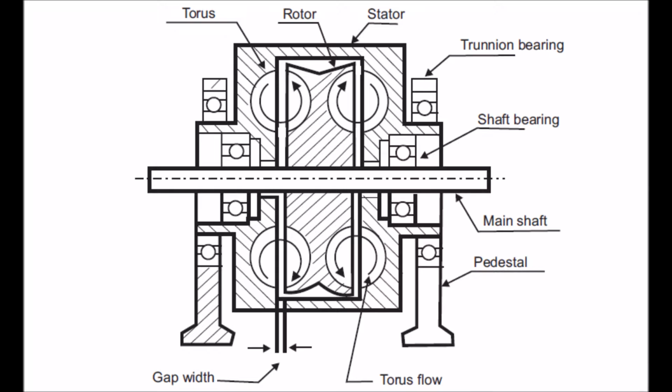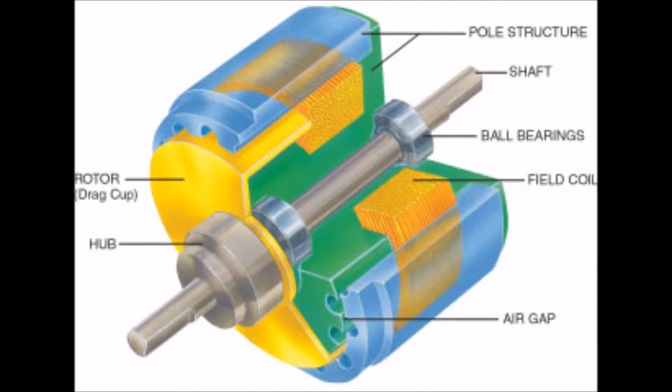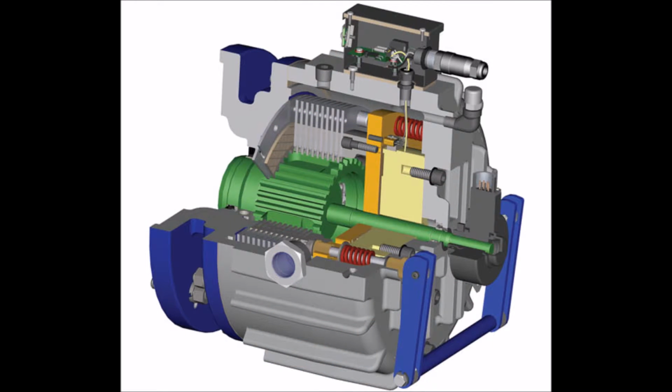A hydraulic dyno is controlled by a hydraulic pump, which is driven by the engine motion. The outflow nozzles open and close at various diameters to provide different levels of resistance. A hysteresis dyno is controlled by a steel rotor which is spun through a variable magnetic field. Electromagnets resist the rotation with respect to the strength of the field. An oil shear dyno transmits torque by having oil between a brake and a rotor. The torque and power are measured from a variable clamping pressure between this brake and rotor.